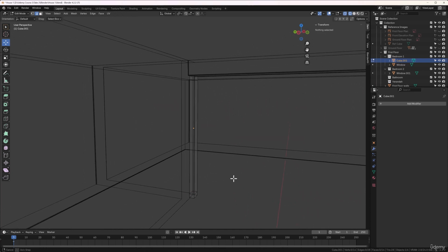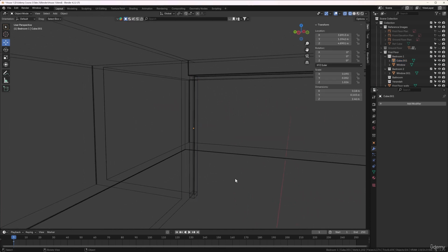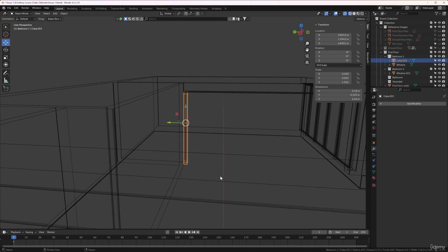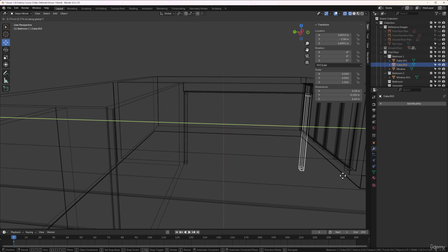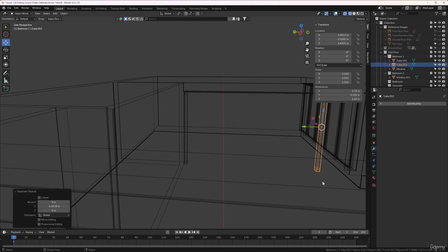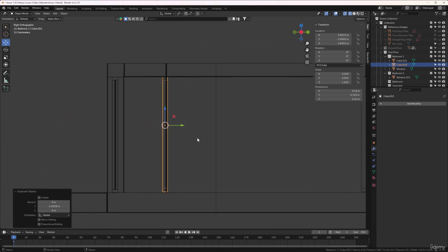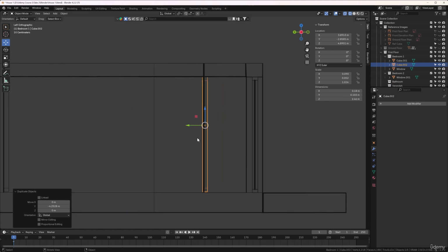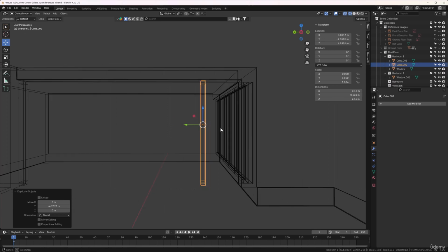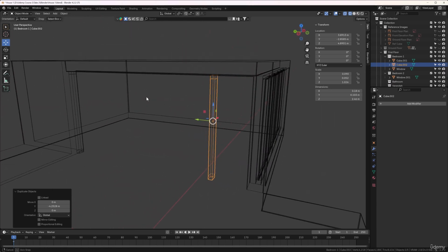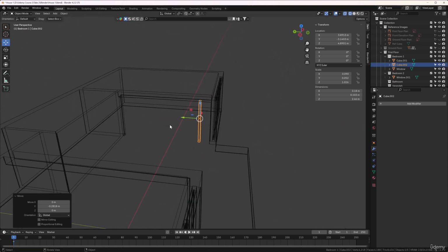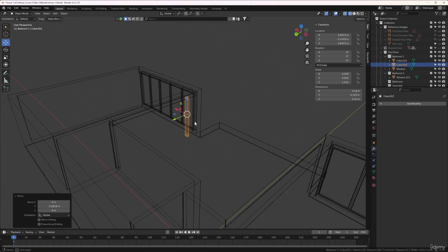I think that's good. Now that I've done that, I'll tap out of edit mode for a minute and I'll grab this and I'll press Shift D and Y and bring a copy across now to the opposite side. To make sure it's in the right position, I'll press 3 on the numpad. And I've got to admit that's confused me. I'll press Ctrl 3 and see if that makes more sense. And it doesn't. What's going on? Oh, I see it now. It's just here like this. We were seeing information from this side, which was confusing me.